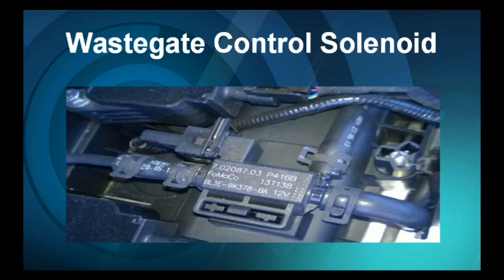Here we have the actual wastegate solenoid that's low side controlled duty cycle that bleeds off the pressure between manifold pressure and the wastegate canister. The computer controls the ground side of this, thus controlling the desired duty cycle. Watching the feedback from the canister pressure and manifold pressure, it has very precise control of the boost pressure.